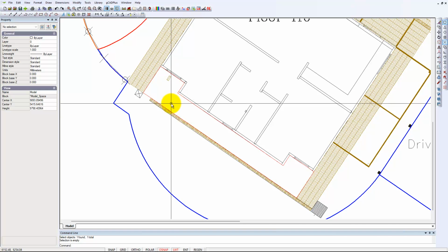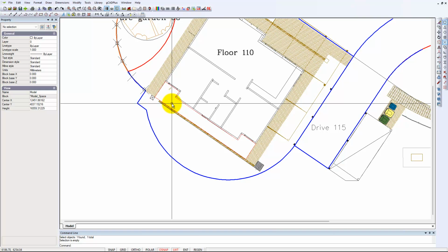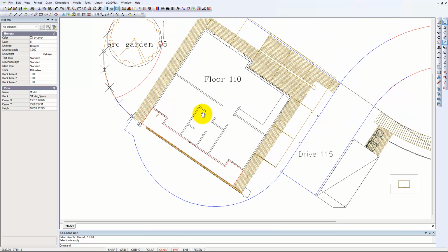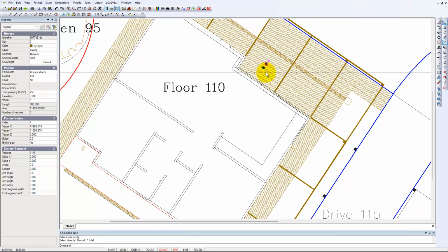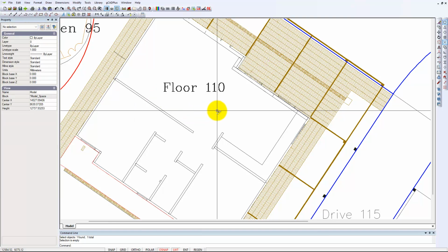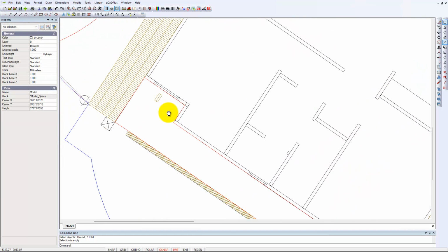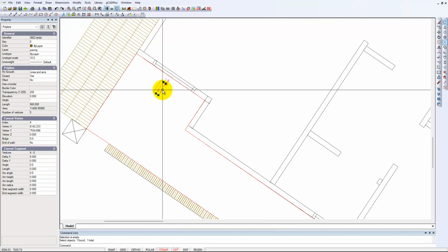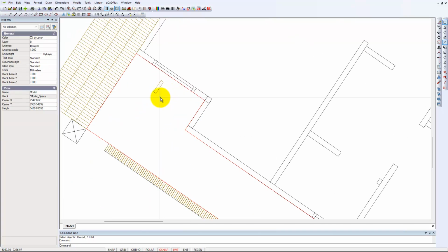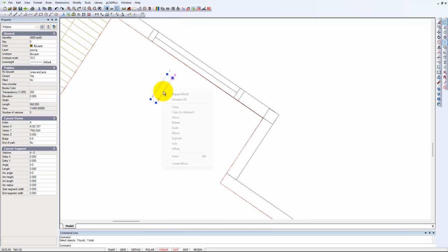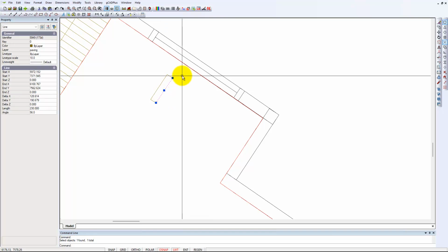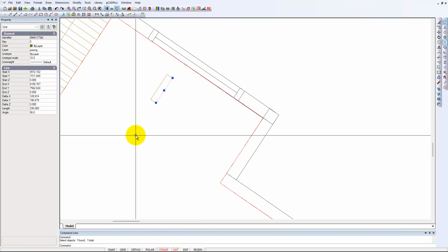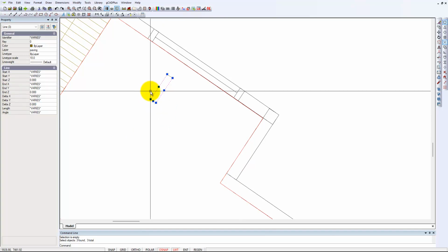And in order to hatch, we need to get an angle. Now, if I look here, this hatch here, and see it doesn't, because it's also been exploded. So we need to know what angle of hatching to put in here. So I've left a couple of these rectangles. Let's get rid of one, and we'll zoom in here and we'll explode it. And then we can pick an individual line that will give us the angle we want. And the angle is 56. So now let's get rid of that.